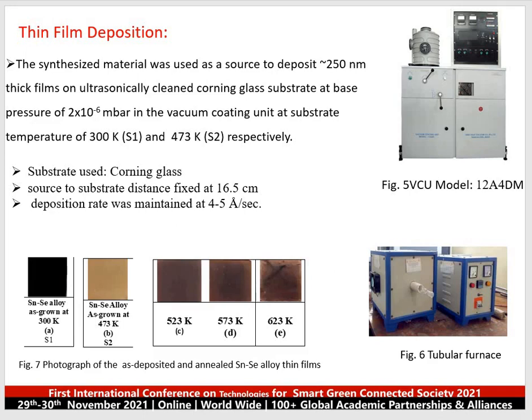The deposition was performed by using single source evaporation method in the vacuum coating unit, keeping the distance between source to substrate fixed at 16.5 cm, while the deposition rate was maintained at 4 to 5 angstrom per second.